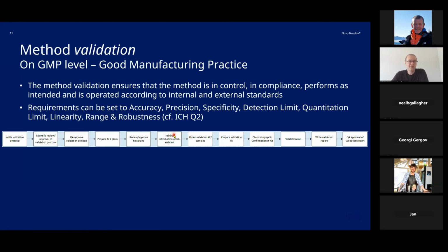For instance, instead of going inline in a full-scale process, maybe you can develop a small-scale process where, instead of taking samples from a large blender, you can make a small blender and then measure on that and take everything in the blender for reference analysis. So that rationale between the PAT samples and the reference samples is extremely important when developing a method that you later want to claim to be valid.